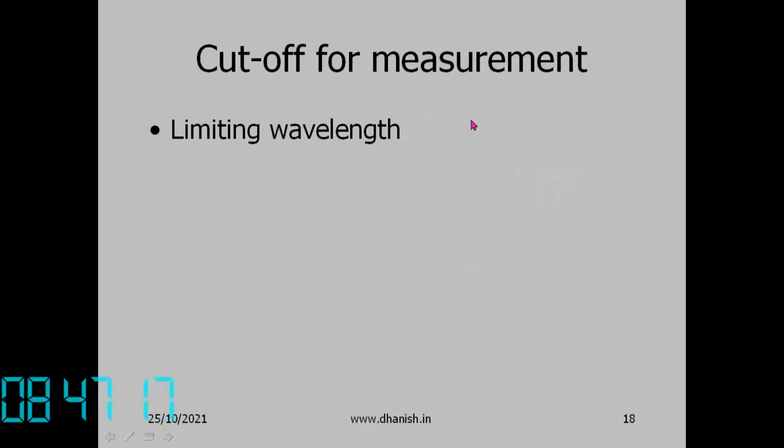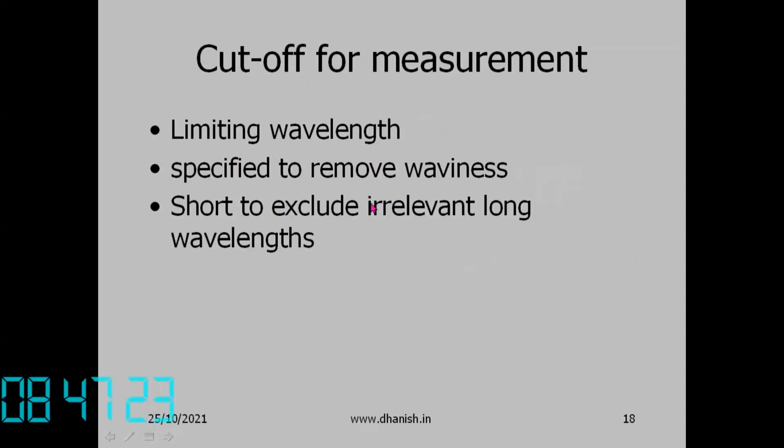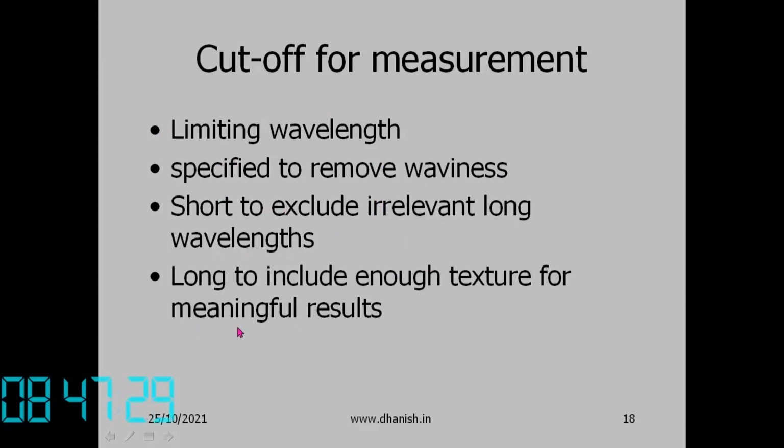So, the cutoff for measurement is the limiting wavelength specified to remove waviness. It should be short enough to exclude irrelevant long wavelengths and long enough to include enough texture for meaningful results. So we have to choose a proper cutoff so that the necessary wavelengths are included.